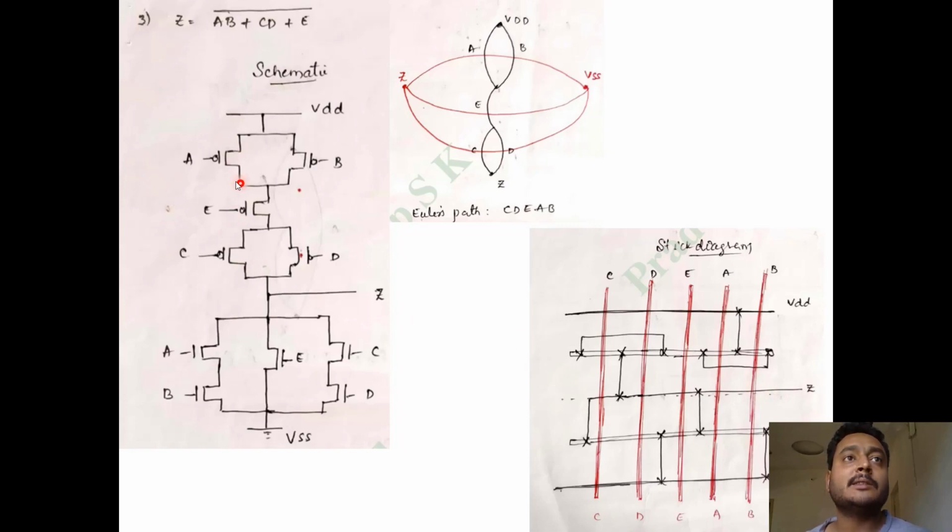And then intermediate connections. So A, B, and E are joined together. So either you should get AE, or AB, or BE. So which is available in this case? Okay, AE is available, right? So A and E is available. I should join one terminal of B to this part so that this connection is finished. So EA is available, take that, and one terminal of B is available. You take that and short them. So that completes this particular connection.